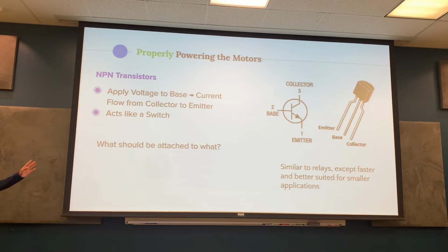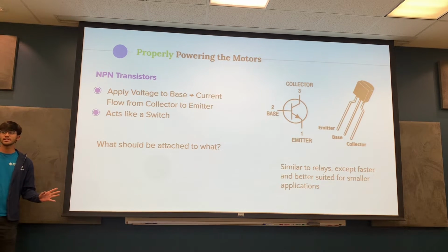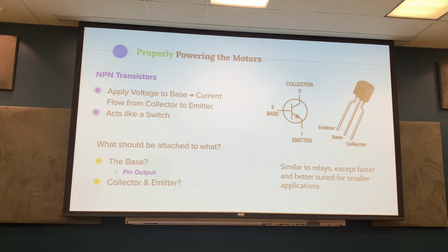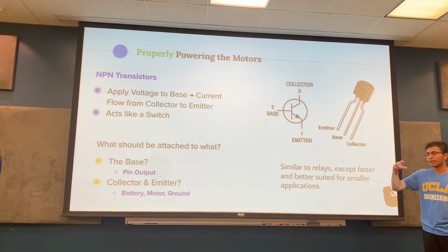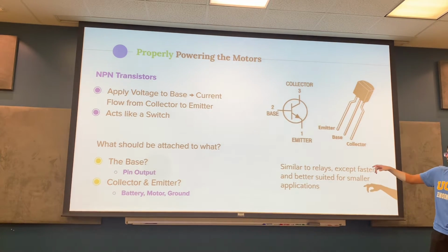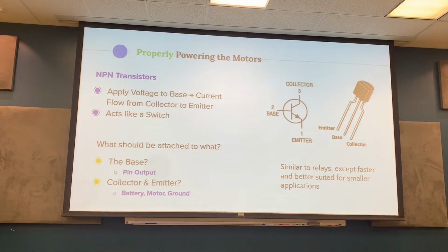Are there any questions about that concept of how a transistor works? No? Okay. To reiterate, we just attach the pin output to the base, so the microcontroller's pin out to the base, and then to the collector and emitter, we just attach the battery and the motor.